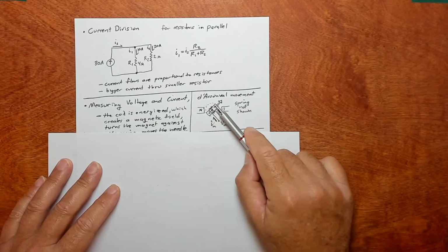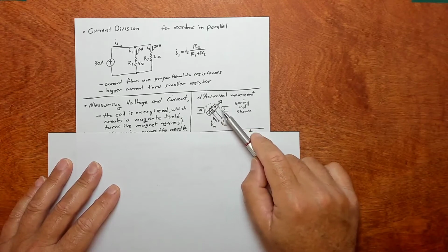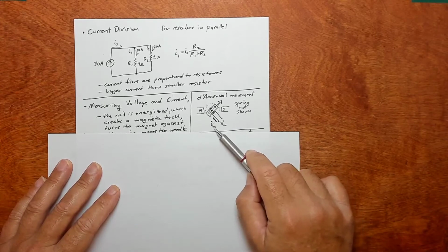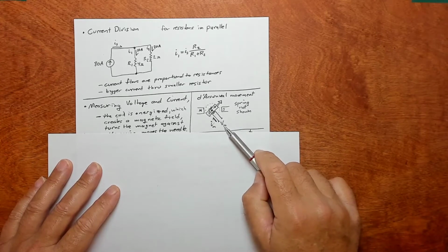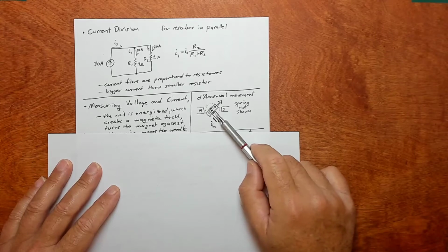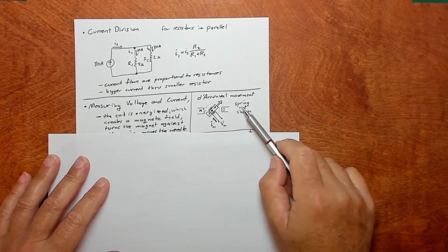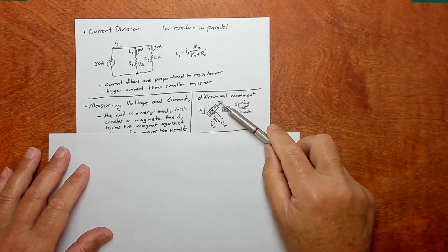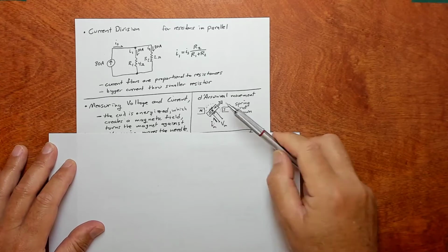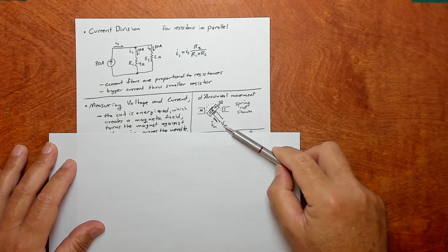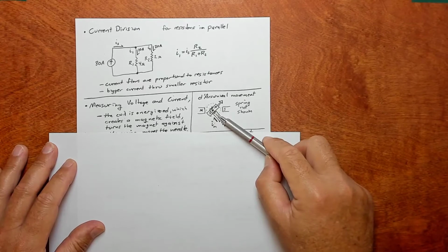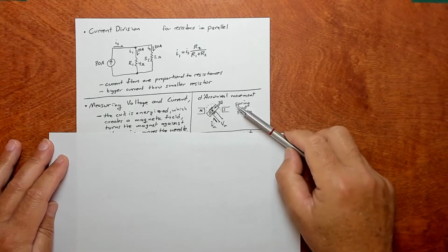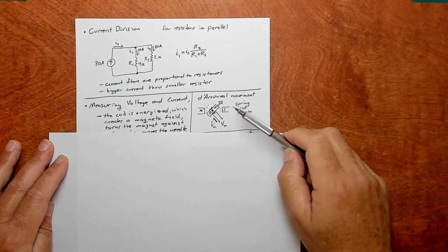So this little magnet here, which can turn, will align with the permanent magnet as the I_m and V_m are applied. There's a spring in there that wants to force it the opposite direction, but I didn't draw that because it gets to be too messy. But anyway, then you stick a needle on this thing, and you can use that for a meter, right? As you increase the I sub m and V sub m, then this thing will twist around trying to align because of the magnetic field, and it'll move the needle. So you can build all kinds of interesting gadgets out of this D'Arsonval movement.